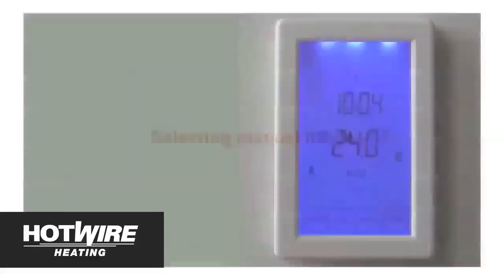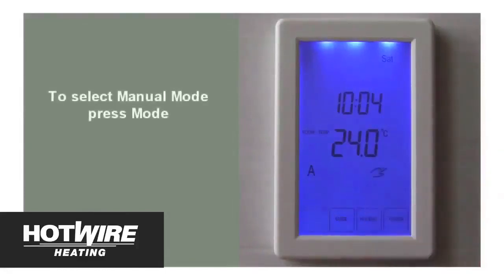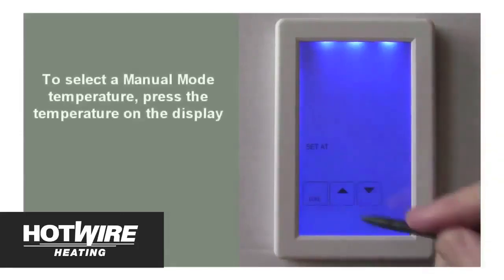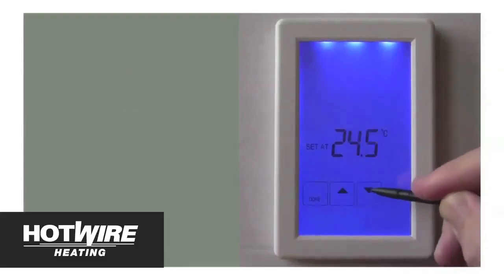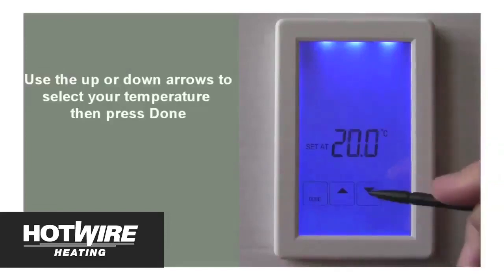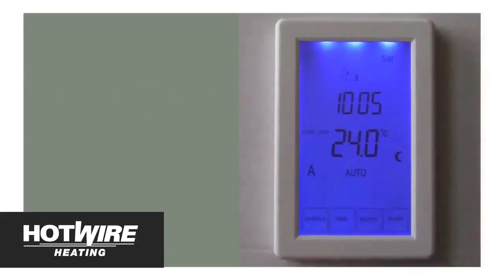Selecting manual mode. If you wish to stop using the automated timer, you can select manual mode. To do so, press the mode button. The hand symbol will appear. Now, the unit will maintain whatever temperature you select. To choose a temperature, press the temperature on the display and use the up or down arrows. In this case, we will choose 20 degrees and press Done. To go back to the automatic schedule, press the Mode button.